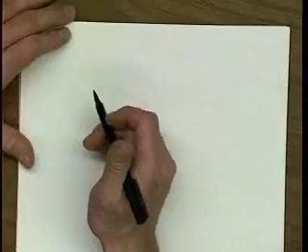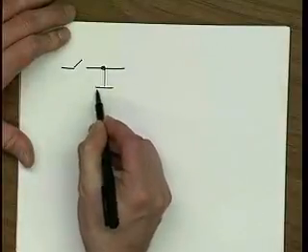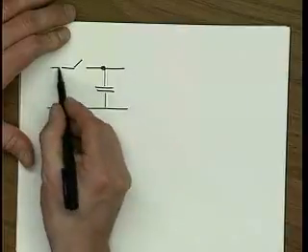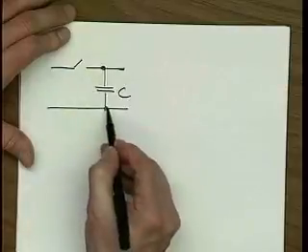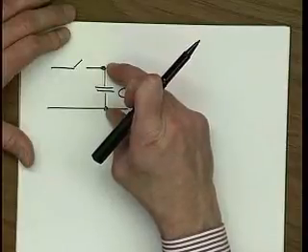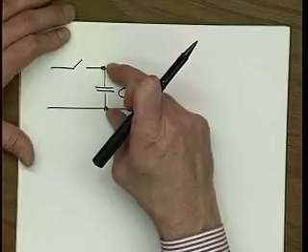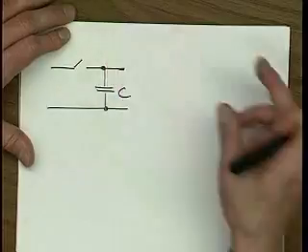So now the model we are going to take for this, that is very applicable to many circuits: instead of having just a switch here, we also have a capacitor. Right? The A to D converter, when it wants to look at the signal, closes this switch, and then when it's done, it just opens the switch, and it keeps the signal and the noise on this capacitor and then converts it. Okay. So if we can figure out what is the noise on this capacitor, we know what noise the A to D converter converts.